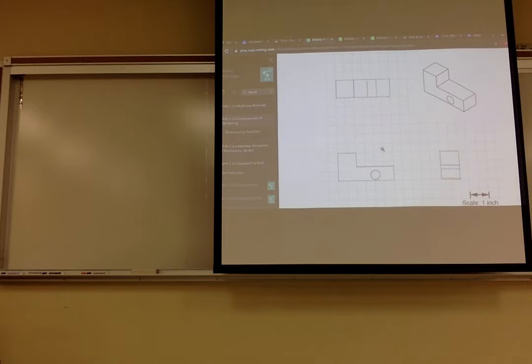So then I'm going to extrude that shape, but I want to remove the material. I don't want to add stuff. Well, what depth? Well, from the side, that big rectangle only goes down 1/2 inch. So that's how you figure it out. Then I need to do the smaller one. Well, you can draw that rectangle in the corner of 2 and 1.5. You're going to cut it 1 inch.